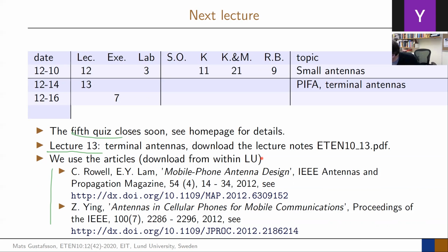We will also then talk about one modification of your patch antenna, which is called a PIFA, a planar inverted F antenna, which is a very popular antenna when you try to make a small device radiating close to a larger structure. This is happening in many sensors and sensor networks that are built, where there is a sensor and you need to put an antenna in it. The antenna has to be physically quite small, sitting maybe in the corner, but you can use the entire sensor to radiate. And the PIFA is a very good design for those ones. That we will also talk about next week.